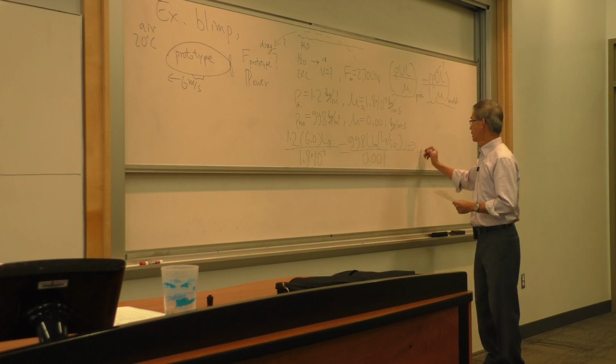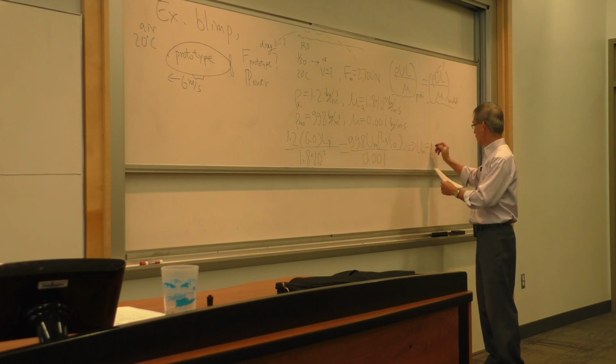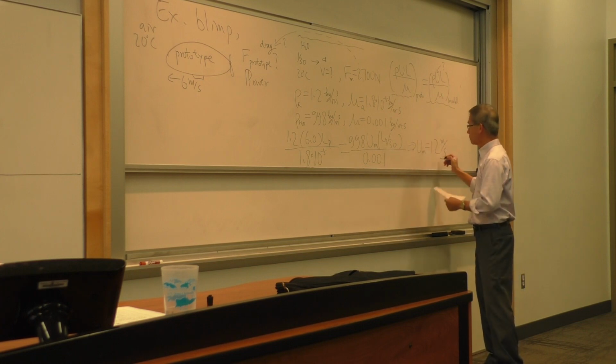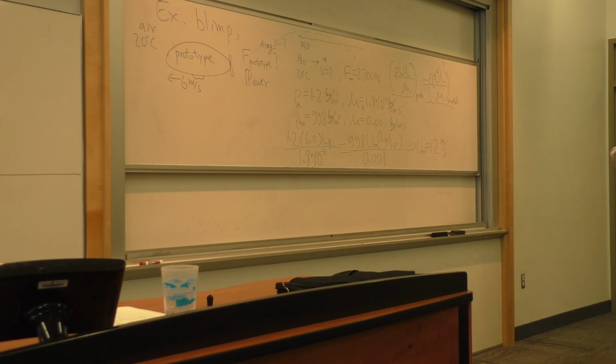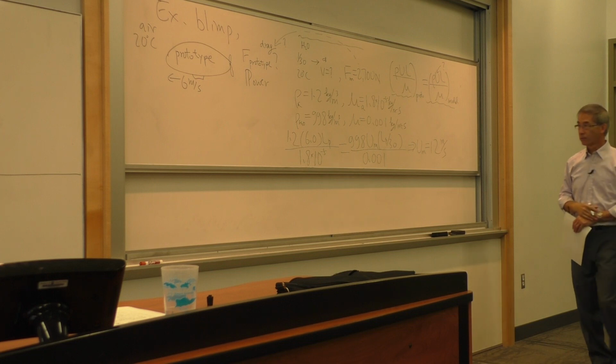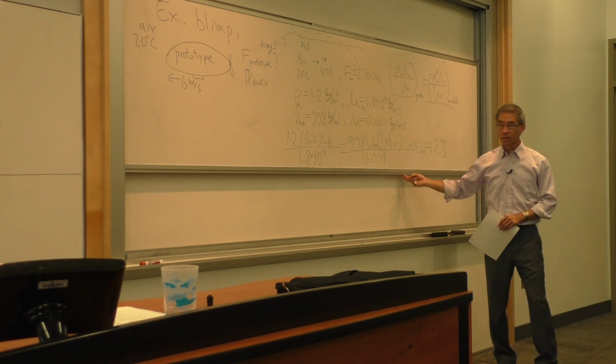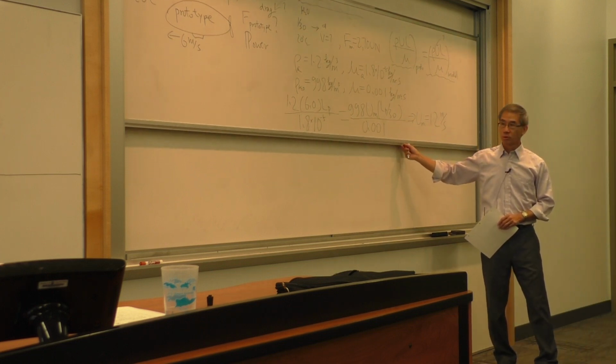So this simply tells me, to match the Reynolds number, despite you are now in water, I simply have to run the water tunnel at 12 meters per second, which is very reasonable, quite doable. You just have a pump that is powerful enough to push the water in your water tunnel to get 12 meters per second. It's not too demanding.